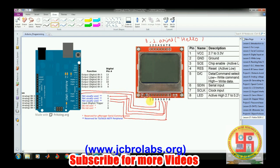And then this is connected to plus 3.3 volt, and this is also connected to plus 3.3 volt, and the last pin, which is pin number 2, is connected to ground. So these are the circuit diagram, or the connection diagram, which shows how the Arduino UNO pins are connected to this LCD. Okay, so now let's come to the coding part of it.